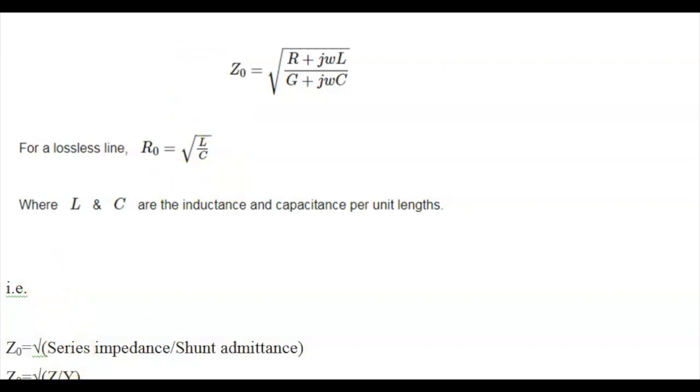So, in two-wire parallel transmission line, we have seen the diagram of a two-wire parallel transmission line, its equivalent circuit consisting of R, L, G and C. And for the lossless circuit, in RF signal, we can take it as an LC circuit removing G and R. And from that we derive the value of characteristic impedance, and that is the impedance measured when the transmission line length is infinity.